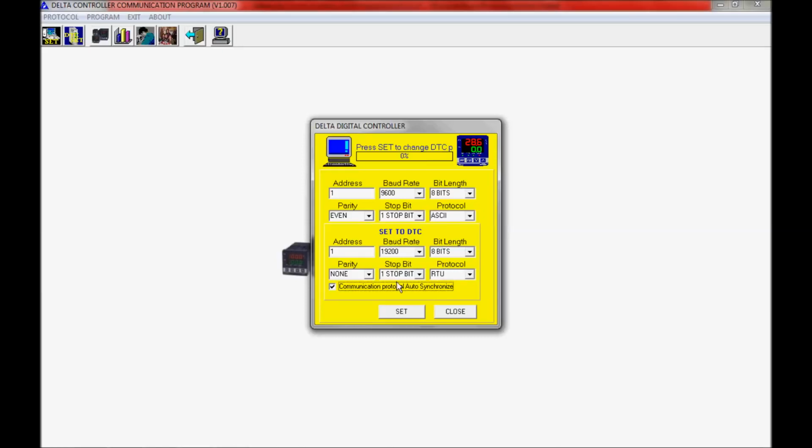So another thing that's going to happen is it's going to start scanning across, and then your LEDs are going to flash again, and you're going to see a banner come across here, and the last one is going to say that the auto synchronization has completed successfully, and you need to power down the controller, reconnect the other controllers, and power it back up, and that will write communication protocol to all of them.